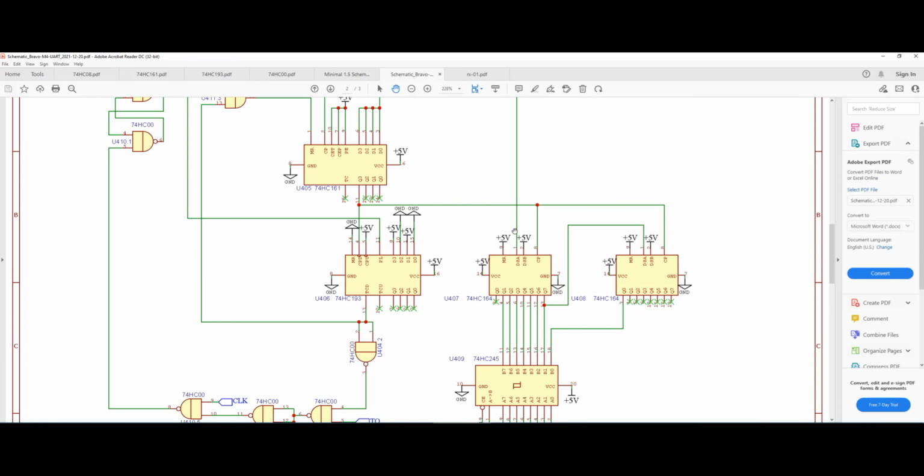And so on. So with each bit of data, we're just going to put it on Q0 and shift one bit to the right. So now, if you think about it, we have a low signal which comes in, and after that, we're going to have 8 bits of data, and finally, we're going to have a high bit, the stop bit, right?